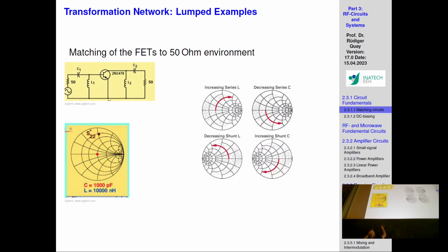So we're here, we moved to here, and then we came back here, and now we made another jump with our C. Now when we're here, we're quite close to the 50 ohm, but not exactly. That's why we add another C. And when we add another C, we're reaching this 50 ohms part. But before we forget, before even connecting it here, we have a problem.